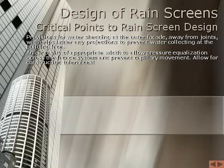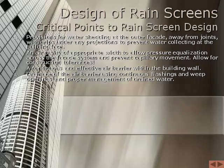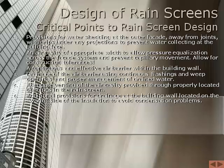Allow for construction tolerances. A continuous and effective air barrier within the building wall. Drainage of the air barrier using continuous flashings and weep openings, and proper management of the drained water. Adequate venting of the air barrier provided through properly located openings in the rain screen. Additional provision for drainage at the building wall located on the warm side of the insulation to avoid condensation problems.